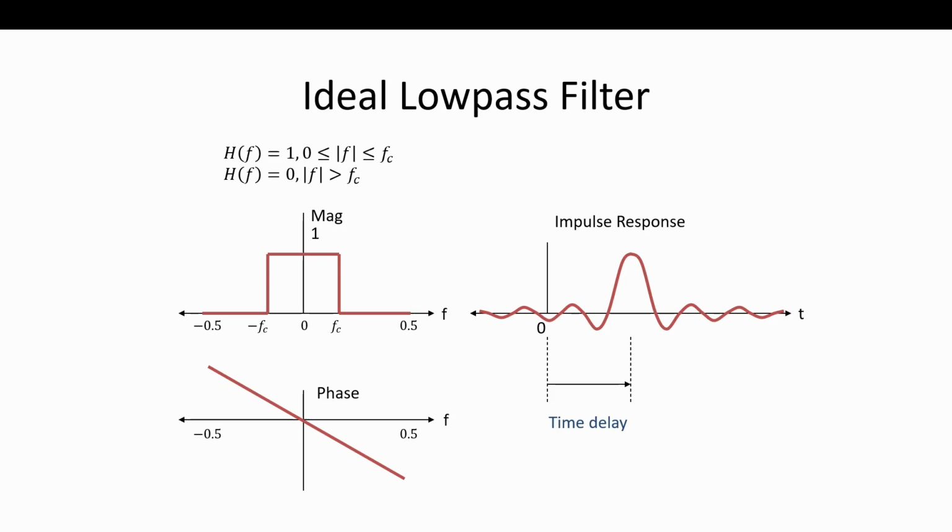If you take a fixed length of cable, and you picture the sine wave at the input and the sine wave at the output, and you compare them, if it's a really low frequency, the phase difference as a time delay between them is going to be very small. Then as you keep increasing the frequency, that fixed delay will be more and more cycles as the frequency goes up. So we would see exactly that: the phase increasing negatively, and that means a fixed delay. That's what a linear phase filter looks like. That's what they mean when they say linear phase.